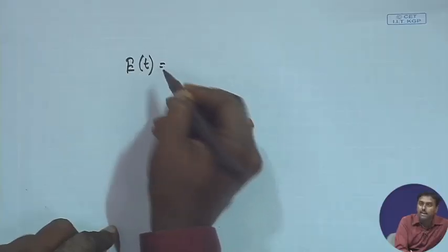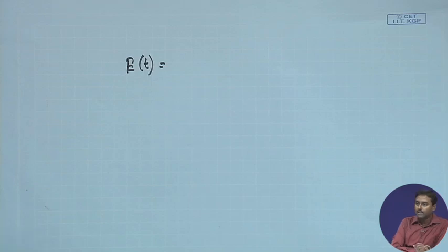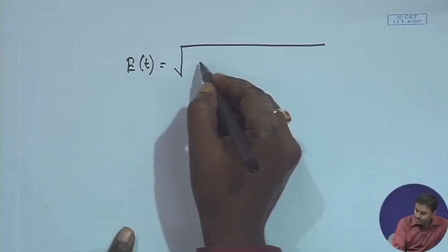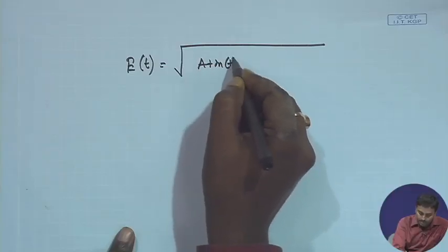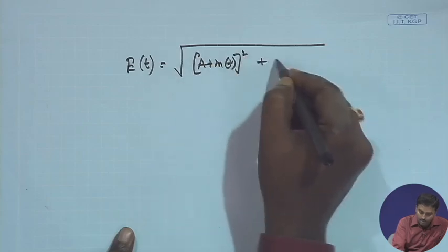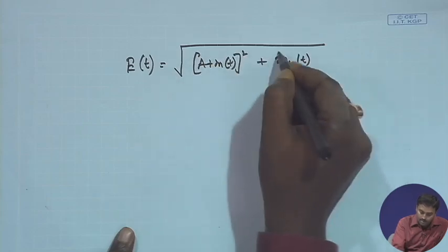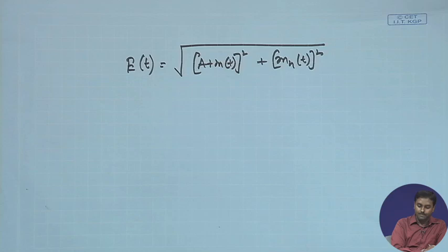So, now let us see if the envelope detector gives me the signal back, that is what we are trying to do. So, if that is E squared, then what is E(t)? Because this is the envelope I will be detecting through a diode detector. If I just pass it through a diode detector and then charging, discharging the way I have designed it. So, if I just do that, that should be square root of (A plus m(t)) whole square plus (m_h(t)) whole square, right.